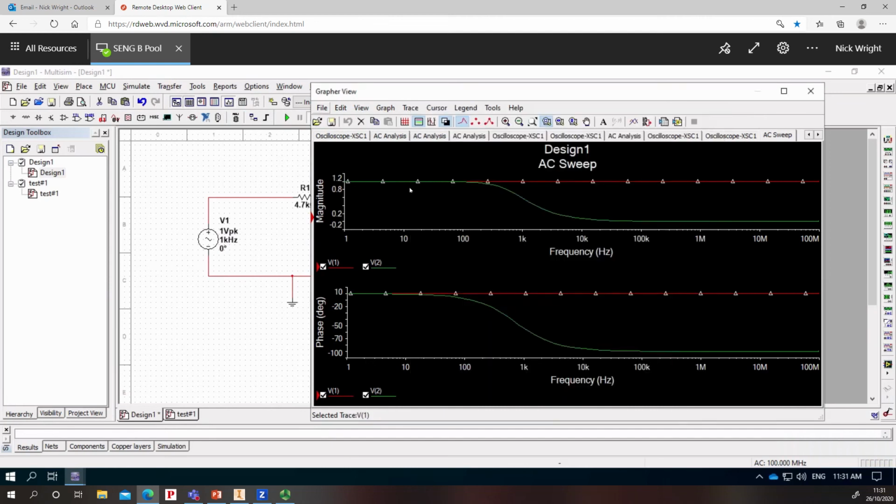and that then shows you a little bit more clearly that the voltage coming out at the output point is going down as the frequency rises. So below 100 Hertz, the filter passes everything. It starts to decrease. By the time I get to 1 kilohertz, it's a fair way down already, and by the time I get to 10 kilohertz, hardly anything is getting through the filter. So this is a low pass filter, just as I'd expect.